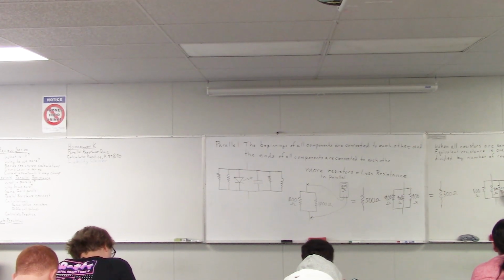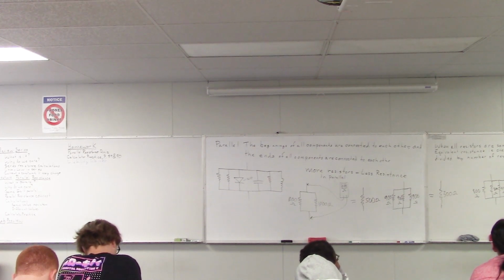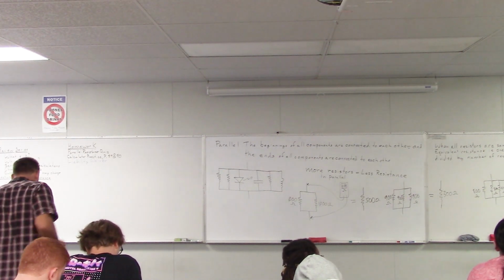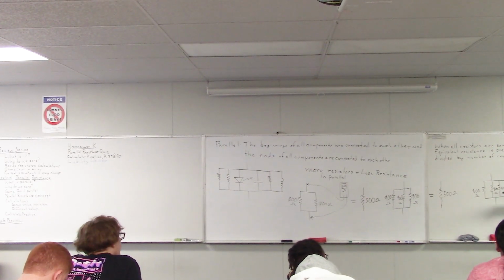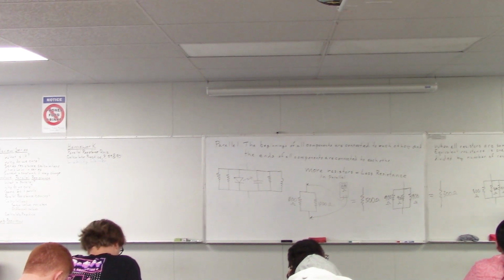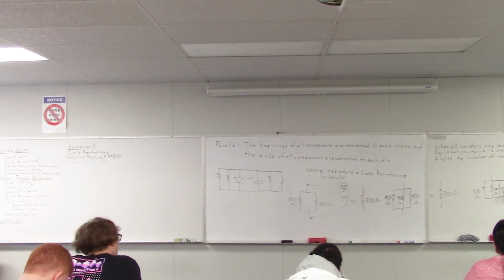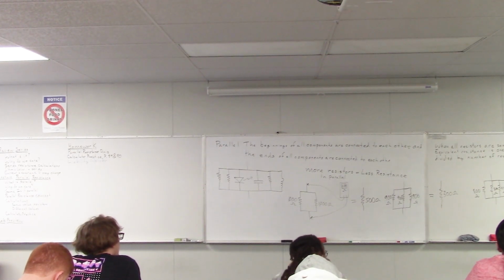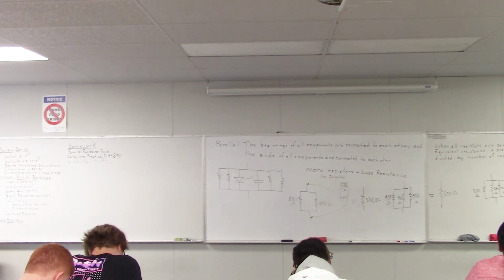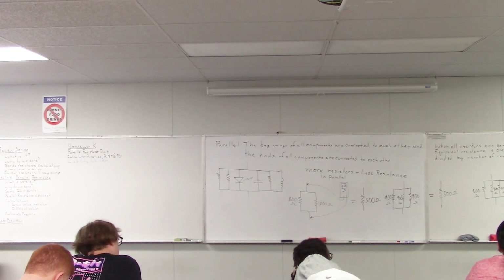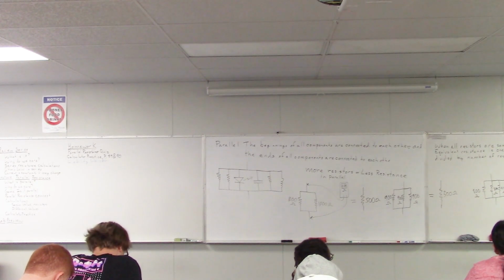So we say that these are all 800 ohms, but like you mentioned, there's a tolerance on each resistor. So these would be, say, 800 plus or minus 5%. One of them might be 795 and the other 807 and so forth. And so this wouldn't be a perfect calculation, but it would get you in the right ballpark. You could be more precise, but this would be a good starting point.